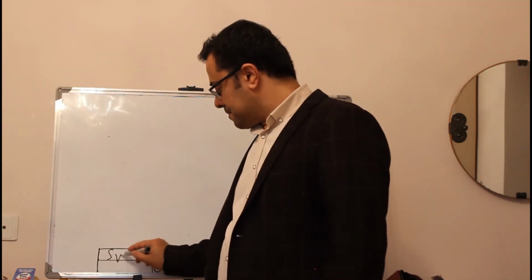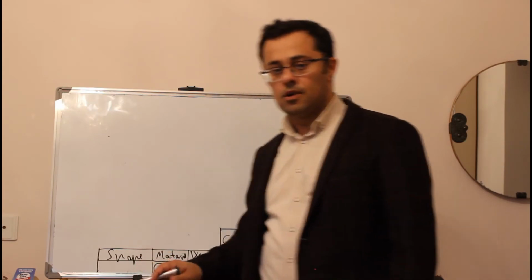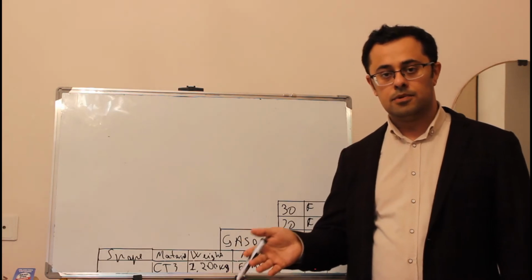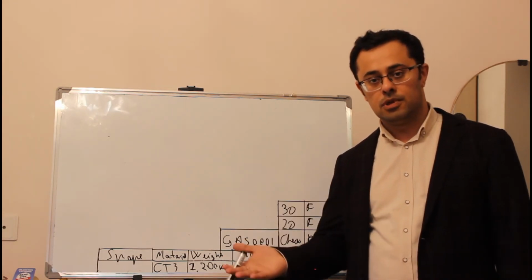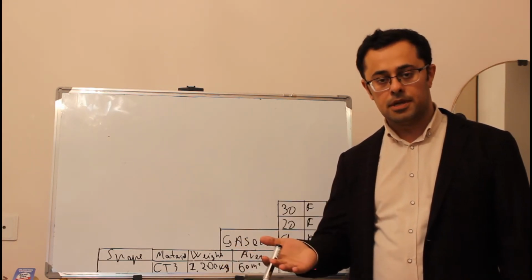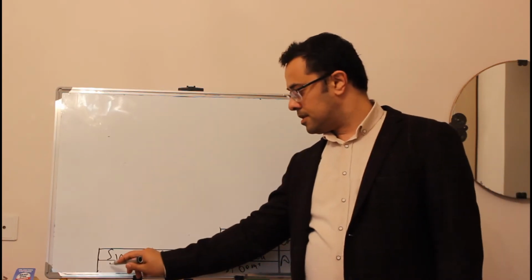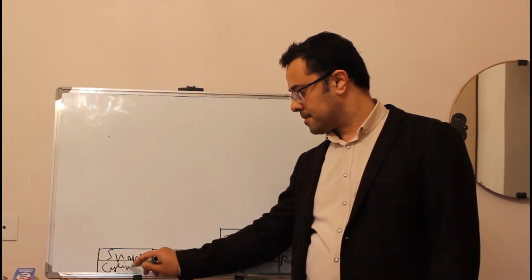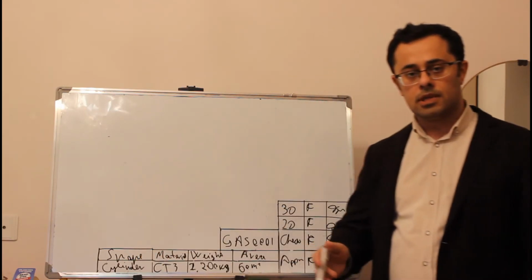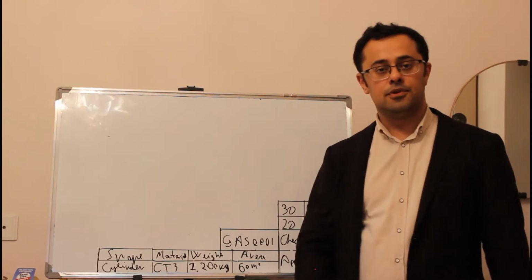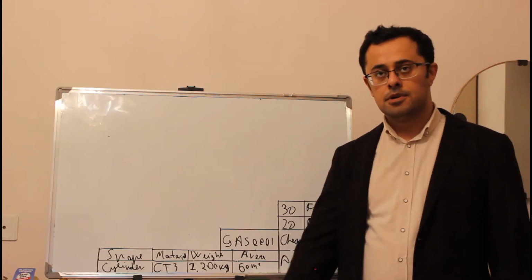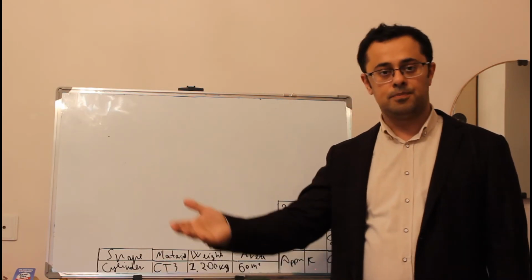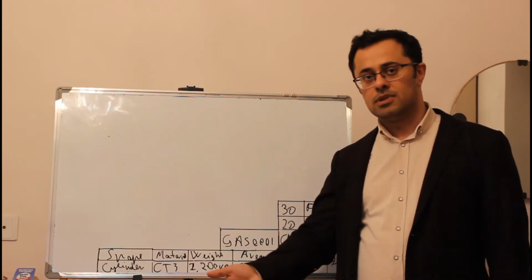Shape. So you can write here, it's a rectangular tube, hollow tube, solid bar, sheet plate. Let's say it's cylinder. What does it give you? What's the purpose of writing the shape? Of course, for general assembly you don't write shapes there, but for parts you should. We'll do it later.